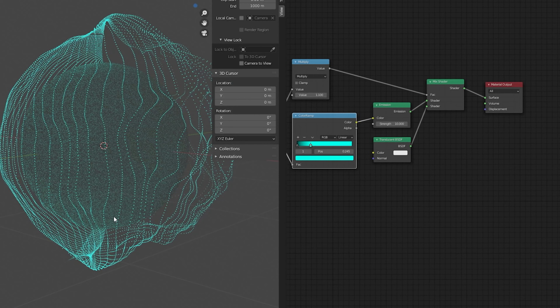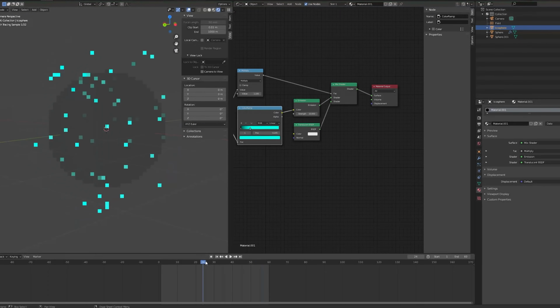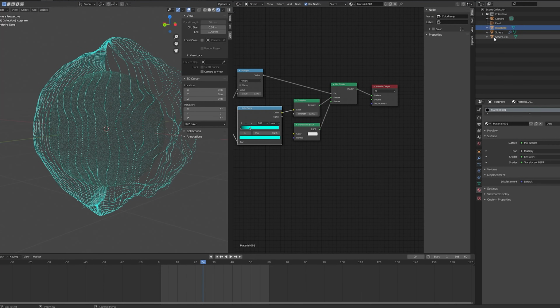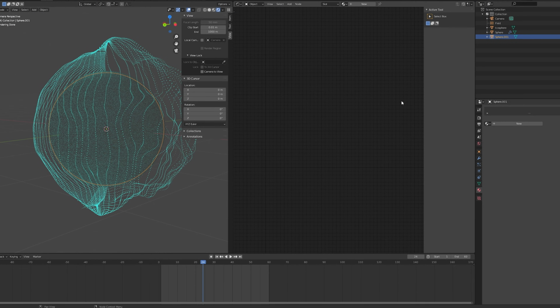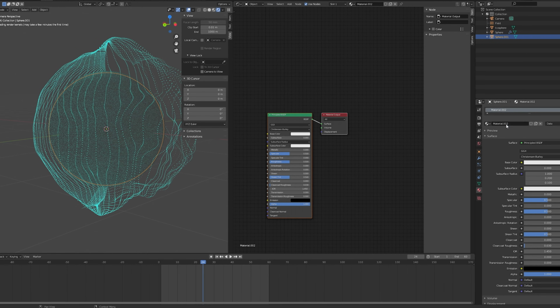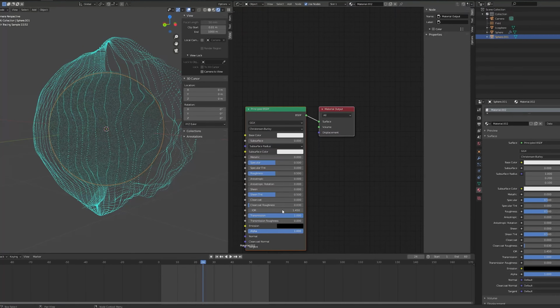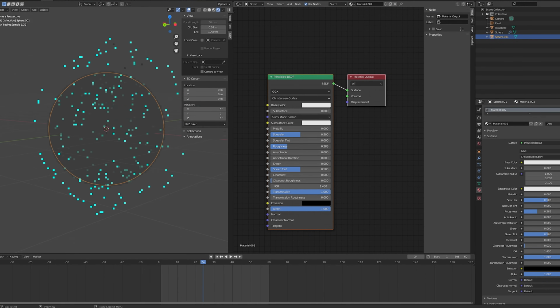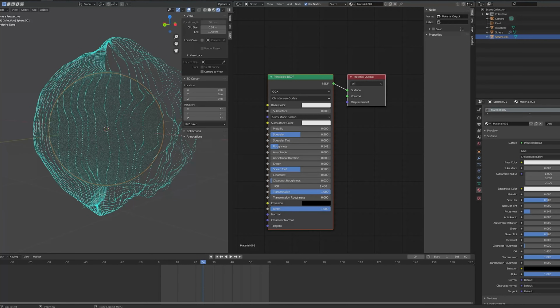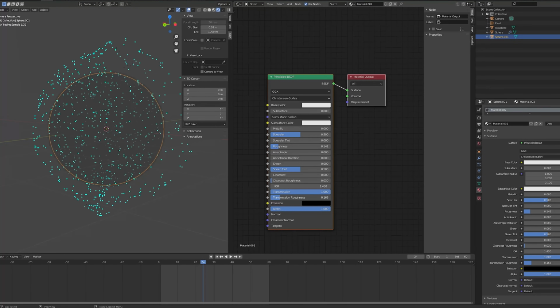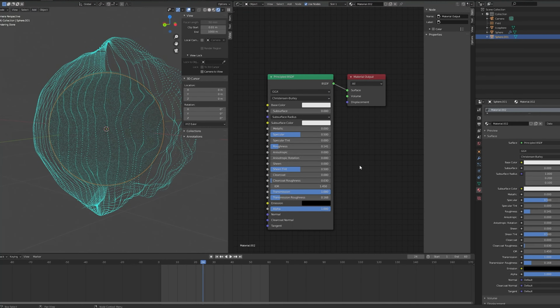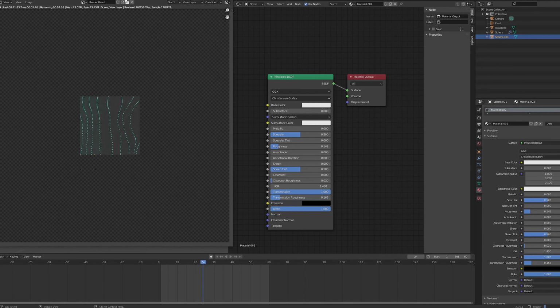I'm applying the glass material for our sphere and emitter after selecting it from the list of objects. Now I add standard material to it, and in settings, let's put transmission to 1, reduce roughness to approximately 0.14, and transmission roughness to 0.17. We don't see any changes in the viewport window since the emitter is hidden in render. I press render image or the F12 key.